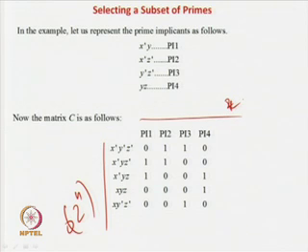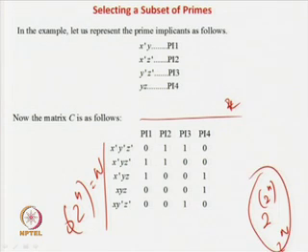And again you have to solve the problem, right? Then you have to find out which of these prime implicants that I take will cover it. That will again be exponential, 2 to the power capital N, if you consider the number of prime implicants to be capital N. So that problem is actually 2 to the power N. So in this case it becomes doubly exponential in the number of variables. So it's a very difficult problem to solve.